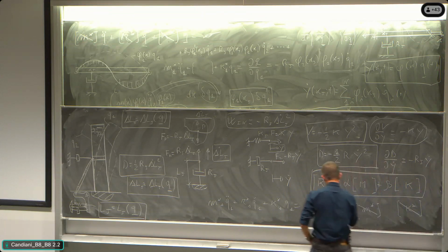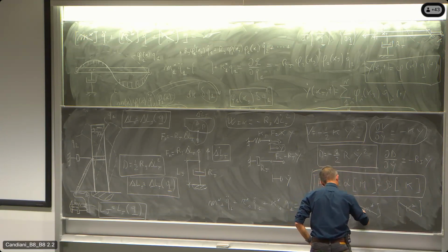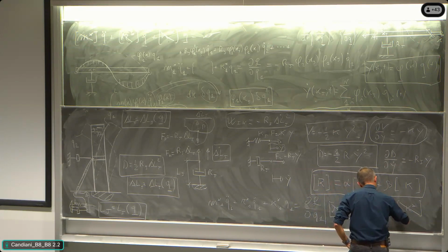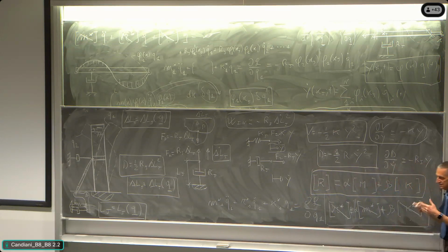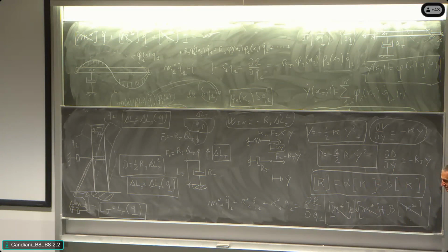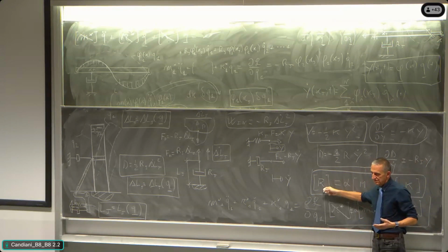And here for the continuum, we say R star is diagonal and is equal to alpha plus beta, where alpha and beta are the two numbers that are stating the way in which we are modeling the modal damping in the continuum, or the distributed damping in the n degree of freedom system.